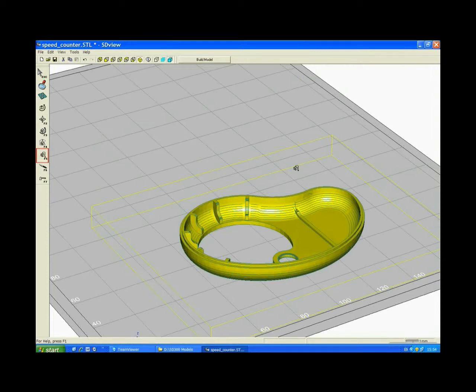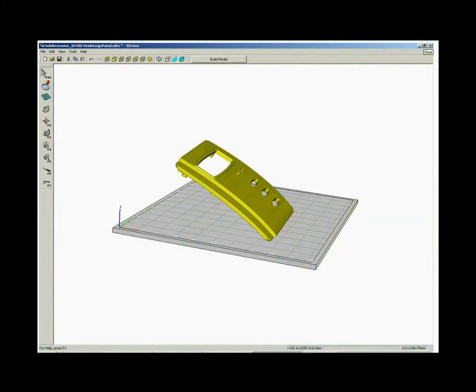This, of course, will occur only when using one of our transparent materials. The other option when using the Align to Face feature is that some STL files are saved as assemblies and arrive to the work table floating in space with only one point touching the table. The Align to Face option allows you to see the part flat in any area you wish.